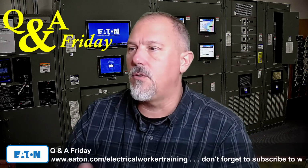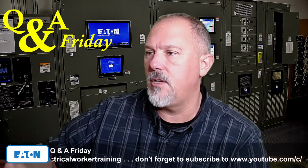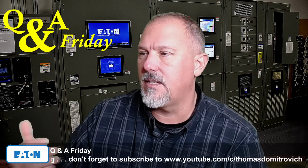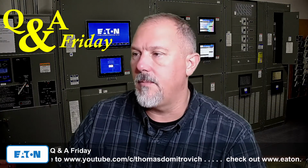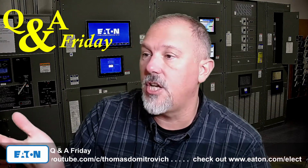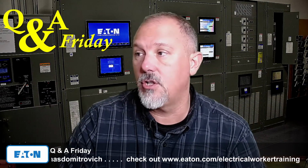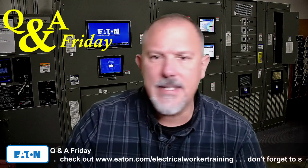A says electrical equipment such as switchboards, switchgear, enclosed panelboards, industrial control panels, meter socket enclosures, and motor control centers that is in other than dwelling units and is likely to require examination, adjustment, and so on. The marking shall meet the requirements. It says shall be field or factory marked to warn qualified persons of potential electric arc flash hazards. And B says in addition to A.